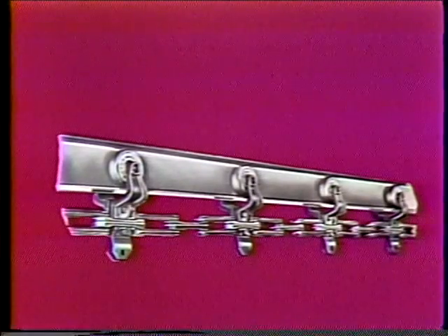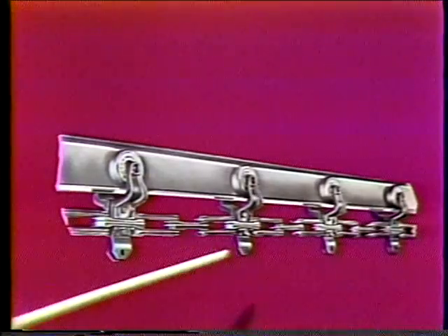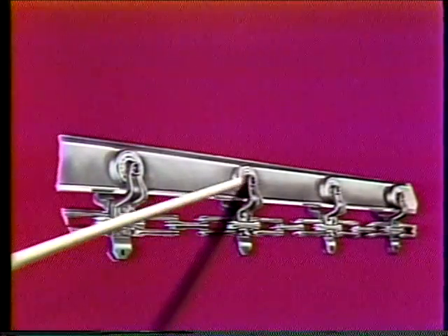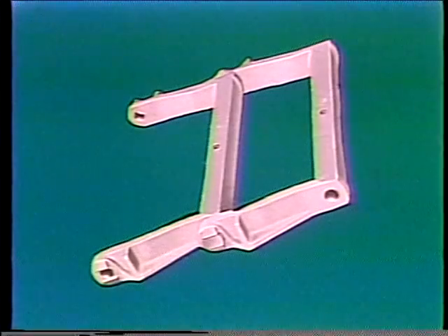In addition to the conveyors mentioned, there are a number of other types. Probably the most common of those which I haven't discussed yet is the overhead chain conveyor. This is where a hook hangs down from an overhead chain. This chain is in turn suspended from rollers mounted on an I-beam rail that runs throughout the plant.